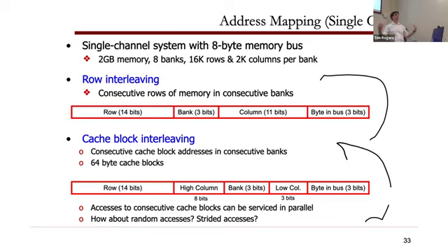In reality, it would be one rank sprayed across 8 chips if each of them only had a small interface. Make sense? That is the magic of a rank, that I can have tiny chips, but bolt them together to make them look like a logically large chip. I haven't really even described rank here, right? I'm just assuming that it's a big chip because that is essentially logically, from the physical mapping of the memory system, what it is. It doesn't matter that it's actually on different chips.